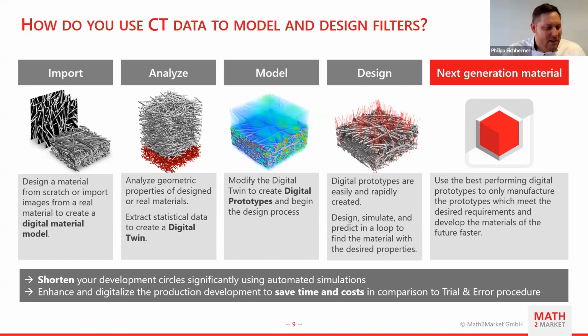Here we change some of the parameters. We change the geometrical parameters, for example the solid volume fraction, or some of the diameters, and we see the effect on filter performance. Here we solve with classical CFD methods. So we have Navier-Stokes equations, and afterwards, to simulate filtration, we have particle tracking, where additional effects like drag, diffusion, and electrostatic forces can be applied. This is where you go into the prediction of physical parameters.